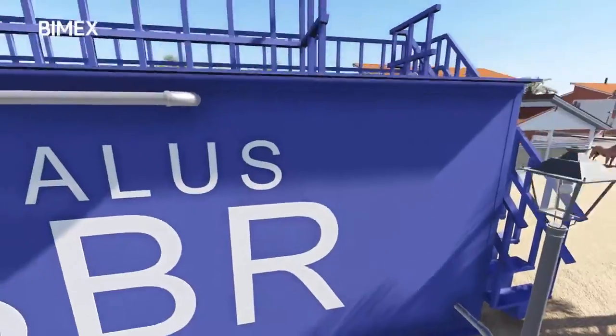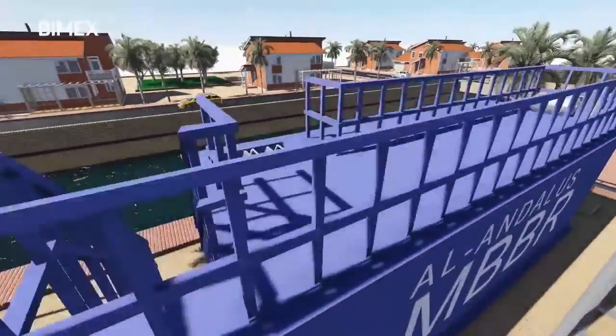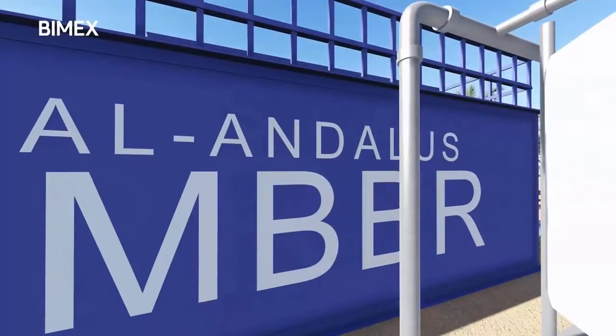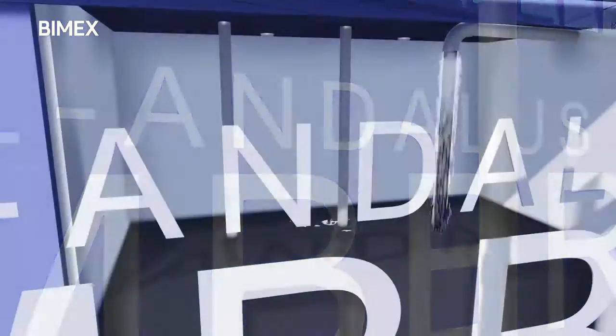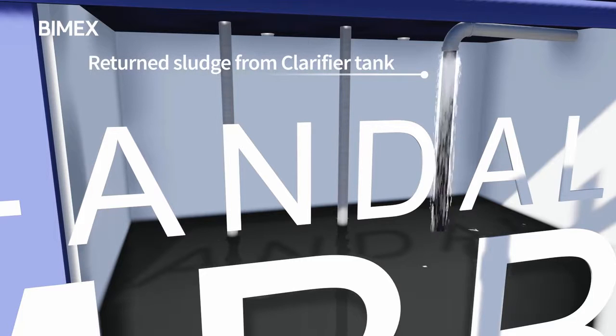Then the fluid transfers to the anoxic tank. Return sludge from the secondary clarifier mixes with the raw sewage in the anoxic tank for denitrification. In the absence of oxygen, the bacteria break down nitrates and nitrites generated in the aeration tank into oxygen and nitrogen gas. This process is known as denitrification.